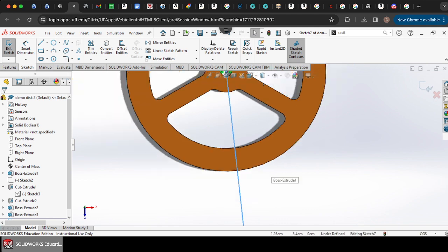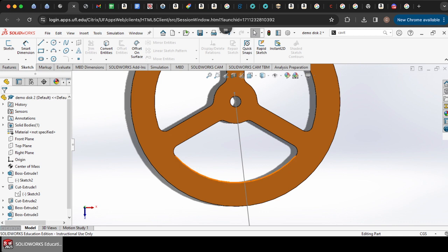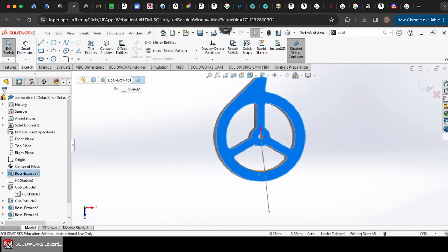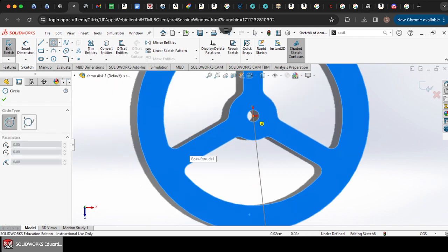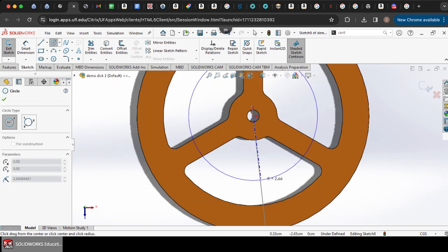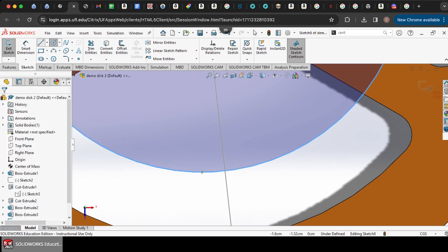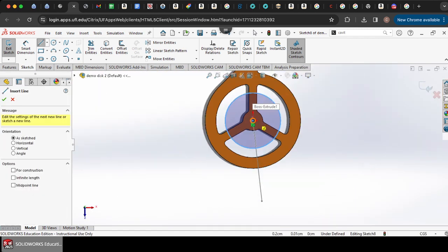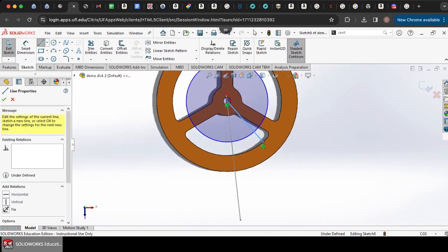So now this line here is going to help us because this tells us exactly where our counterweight needs to be. It needs to be centered around this line right here. So from there we can do what we were doing before, and we can start doing our counterweight guess and check. So let's take this out to, I don't know, like 2.75. I don't know. Like I said, this is where the guess and check begins. We can go ahead and start making the geometry of a counterweight here. So I'm going to take that out to here from the center line.